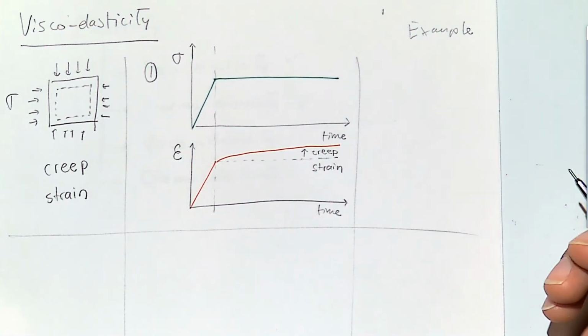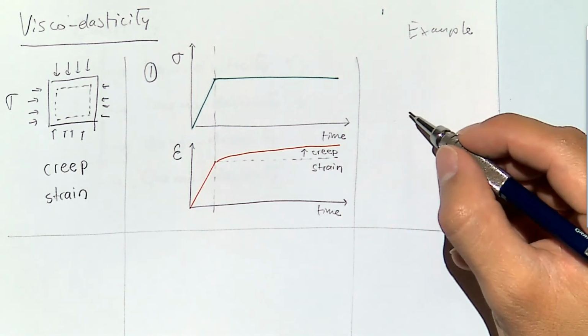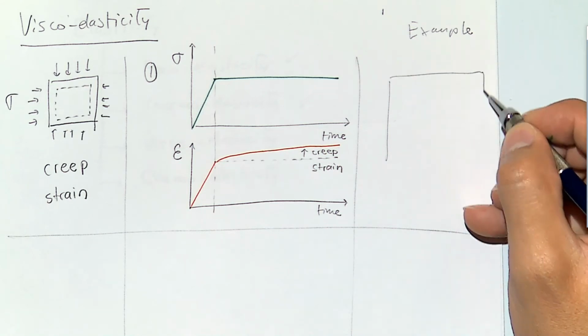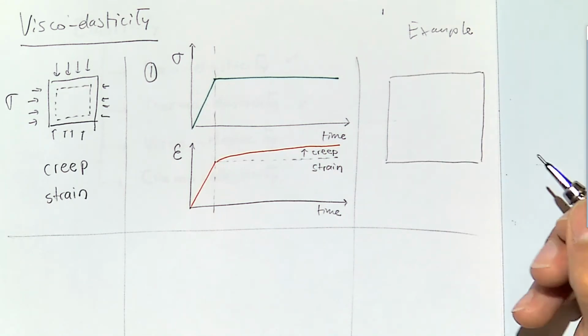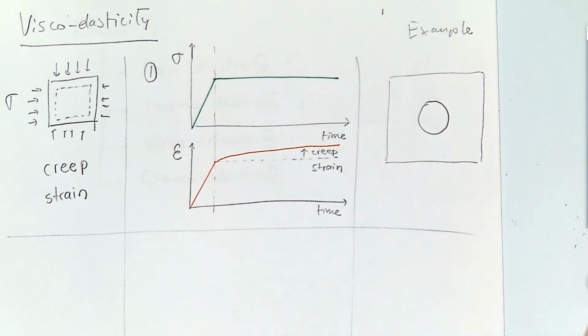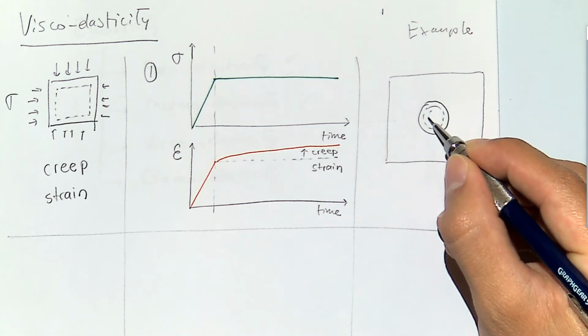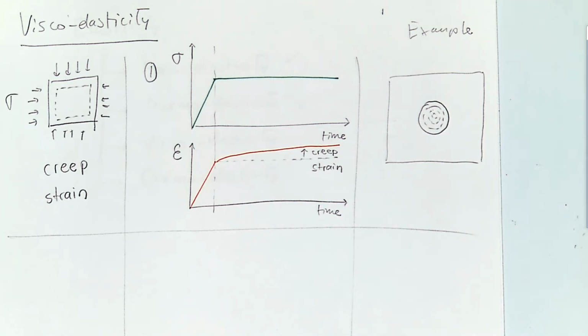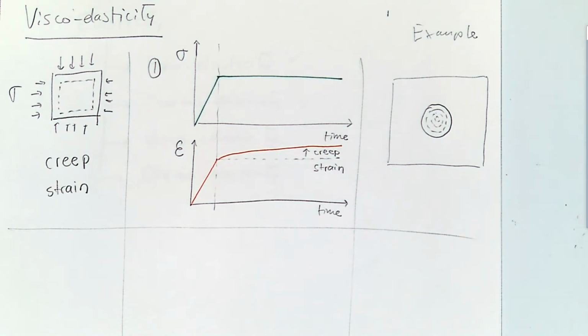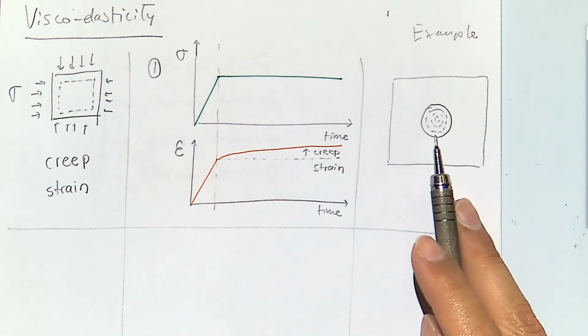An example of this in petroleum engineering is the case in which sometimes you might drill through a salt formation, and if you don't case the hole very quickly, the wellbore may close on you as a function of time, because that salt was very happy with a given state of stress, but now you drill a wellbore, you change stress around the wellbore, salt doesn't like deviatoric stress, so it's going to tend to deform until it doesn't have any deviatoric stress anymore, and the wellbore is going to close.